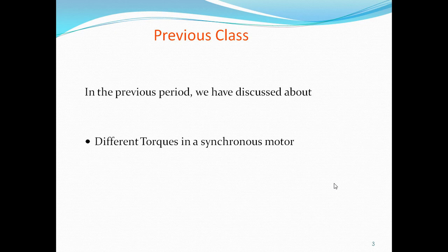At any instant, whether 0, 30, 60, 90, 150, 180, 240, 300 or 360 degrees, the resultant flux is 1.5 times the maximum flux, rotating at synchronous speed.